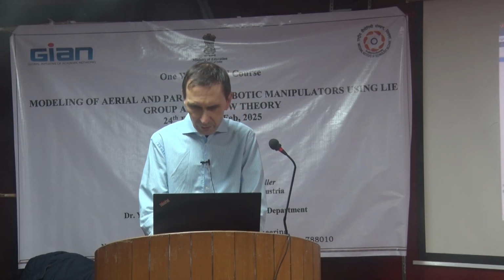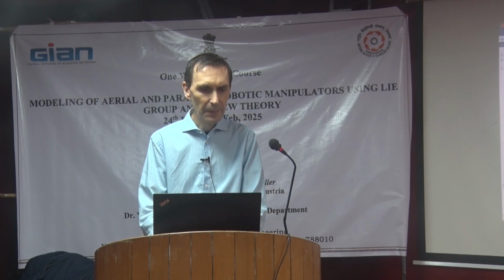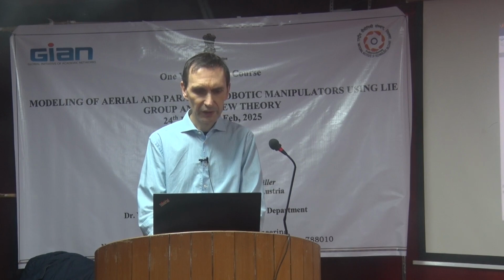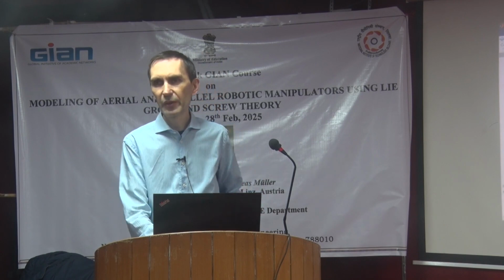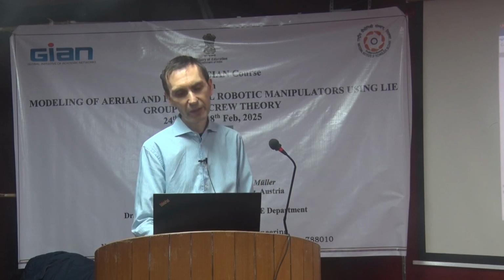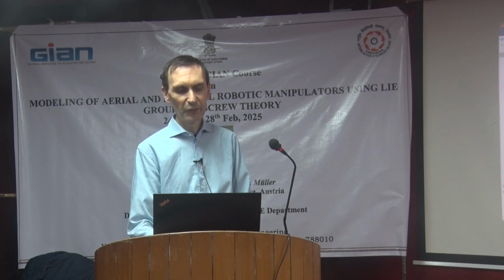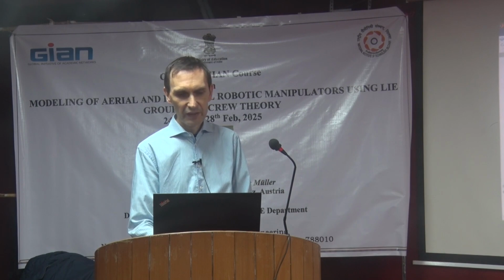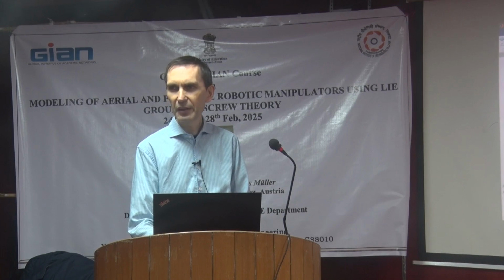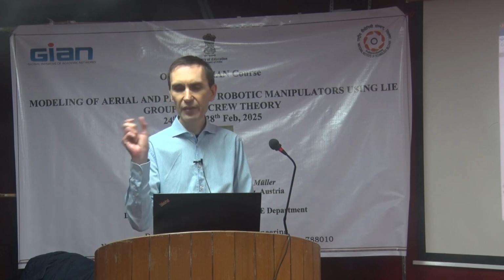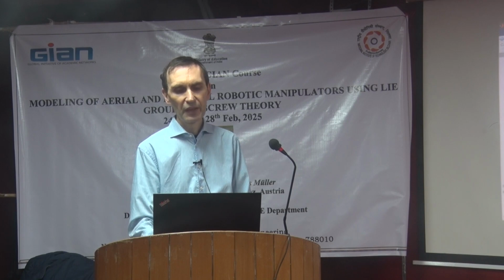I should actually be able to somehow code. Anyway. Example, maybe the planar 2R, the one that we just had, and look at here. So, and what it does is like this. By the way, MATLAB can also do symbolic computations. It's not very good. I mean, it works. It's not perfect. For symbolic computation, you better use a different package. Do you know how to do symbolic computation in MATLAB? Yeah. So I say we have the parameters L1, L2, the lengths, and maybe the joint angles Q1, Q2. And I just say this is a symbolic real number.